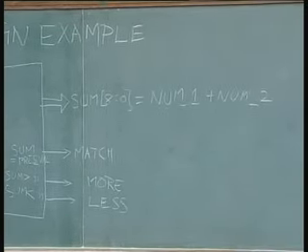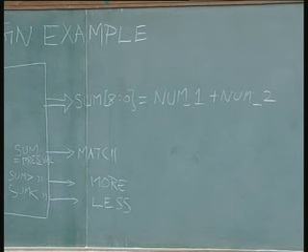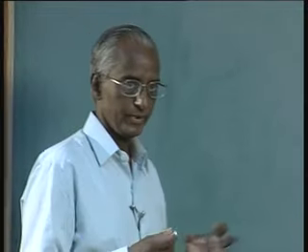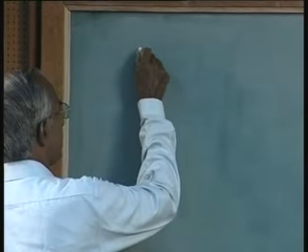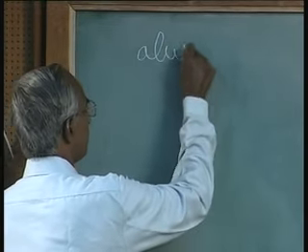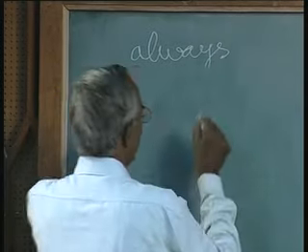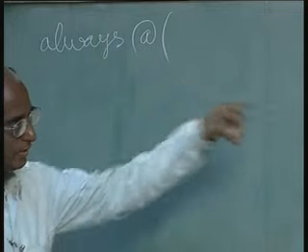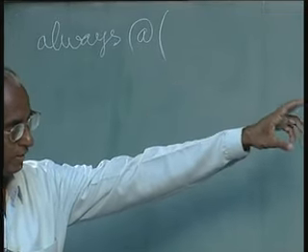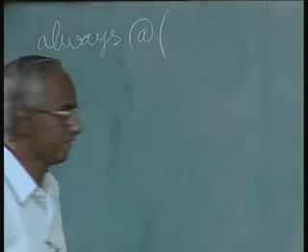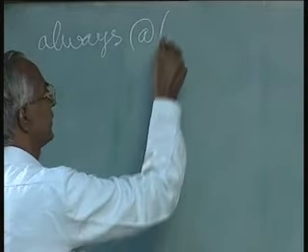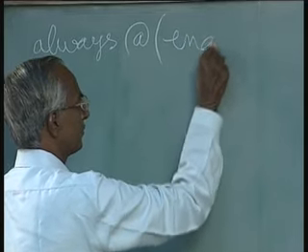We can use assign statements for this, but however the always statement is a better thing, because we need to take action only when there is a change in the inputs. So, we will use the always statement as such. First in this always block, you say always at, this is mandatory, and list all the input variables. You should always speak in terms of signals, not variables, that is a C habit, right. So, I will just list this enable sum and all the inputs.